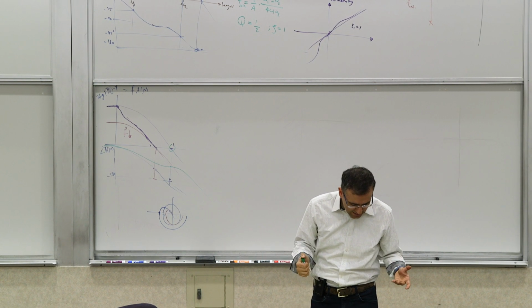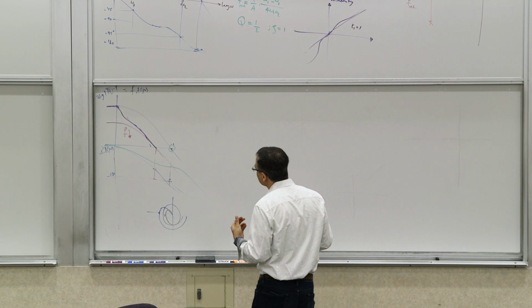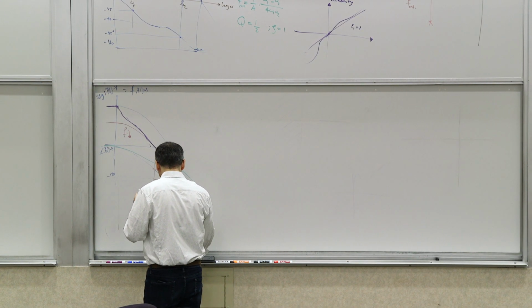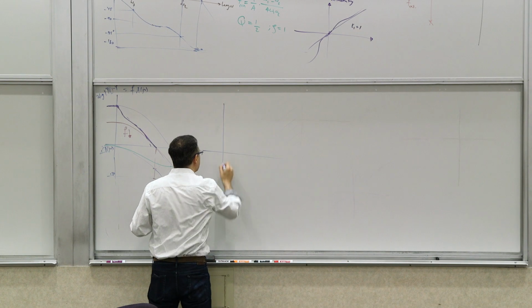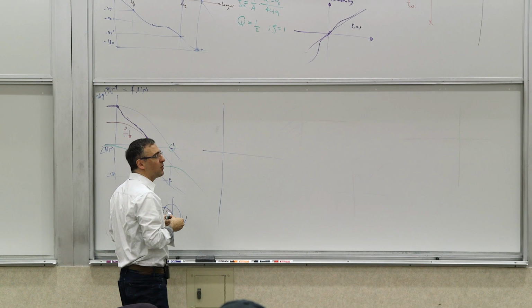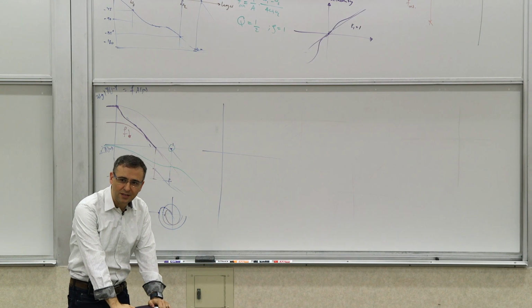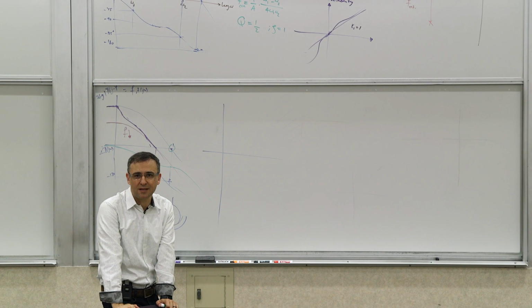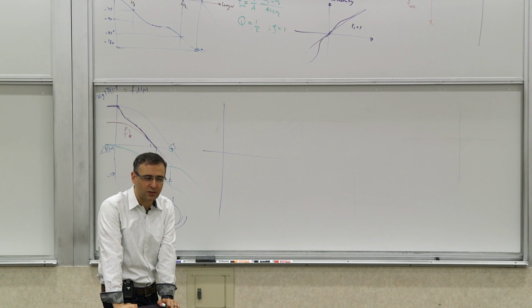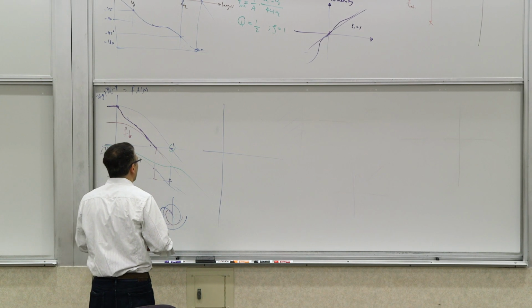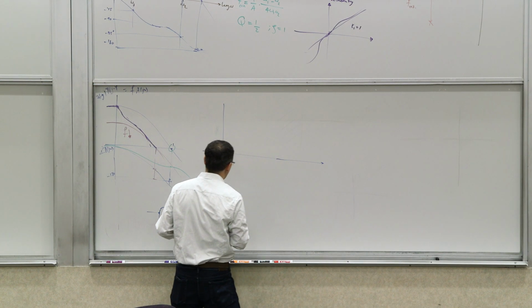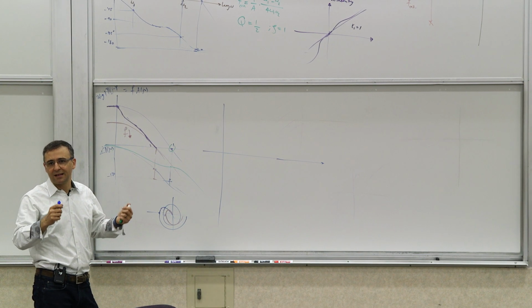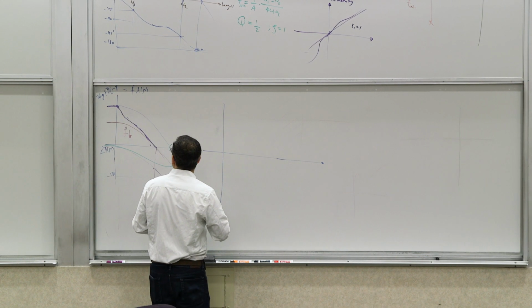So you need to adjust these things accordingly. You can name them different things. But the key question is, let's make it a little bit more quantitative, just a little bit. Let's say you look at this and say, I want to get a phase margin of 45 degrees for the sake of argument. Now, 45 degrees is generally not enough. You typically want something like 60 degrees, depending on what you're designing. Sometimes it's enough. But 45 degrees has an interesting property that we can use, and then we can make adjustments around it. So a lot of times we start our design with 45 degrees, and then make an adjustment later on to make it a little bit larger.